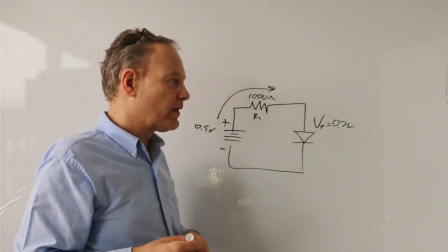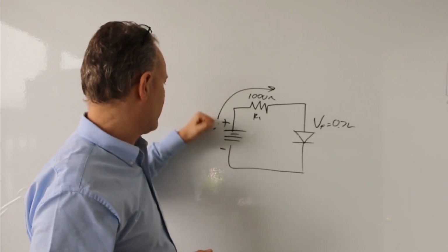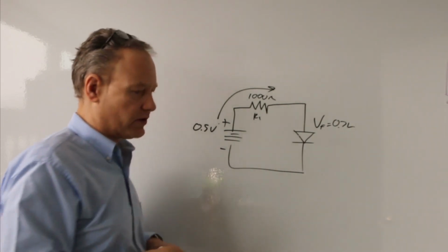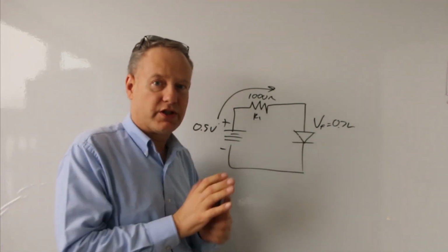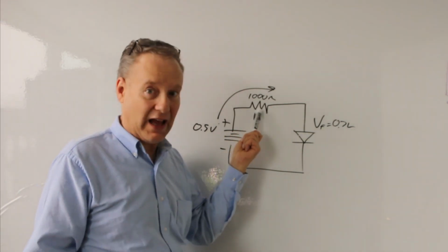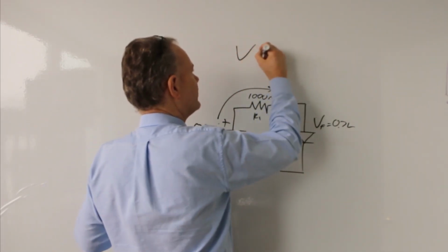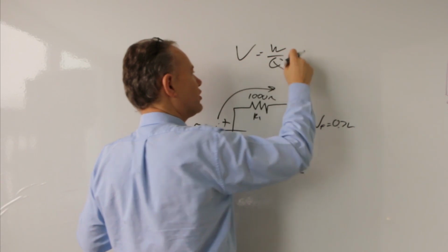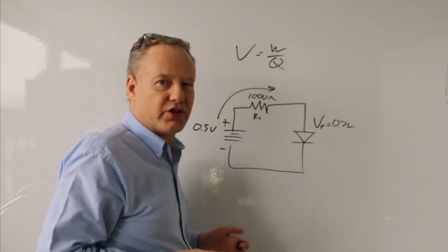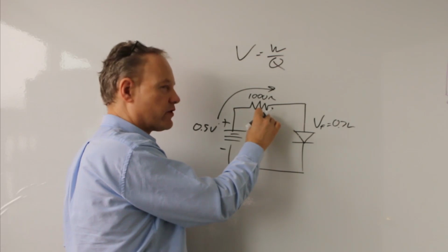This is actually important that we look at, why this is going to say 0.5 when I kick that down to 0.5 volts. If that's 0.5 volts, then this guy is closed. No current is traveling through, and we have no voltage drop across this at all because there's no current going through it. And you know that voltage is the energy pushing the coulombs through. If there are no coulombs pushing through here, then there is no voltage drop. So if that's 0.5, that thing doesn't allow current, and there's no voltage drop across that.